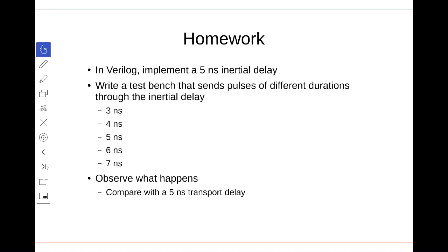The best way of understanding something is by implementing it yourself, so it should be no surprise that this is your homework. You will send through pulses of different lengths through an inertial delay, and you'll be able to see with your own eyes what happens. For the exam, you will need to be able to do this yourself. If I give you a waveform and say, what's the output if you put this waveform through an inertial delay of 5 nanoseconds, you need to be able to draw it yourself. But first, get ModelSim to draw it for you, or an online Verilog simulator. Get it to do it for you first, and then you can learn the trick yourself.